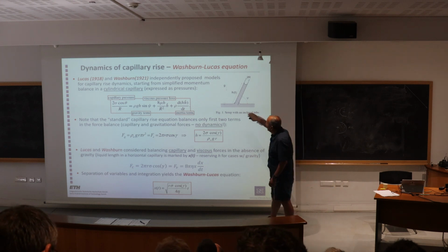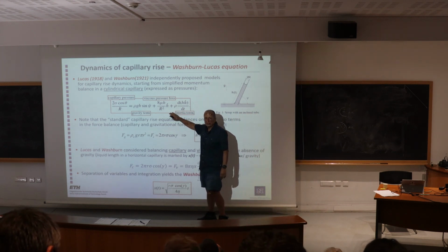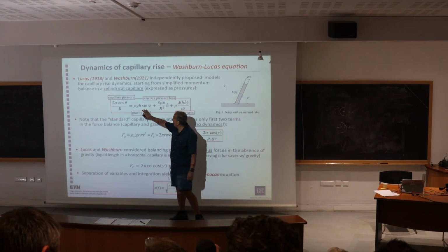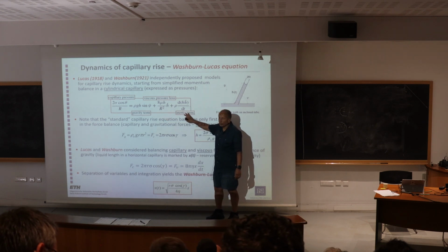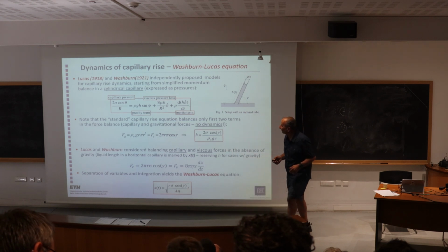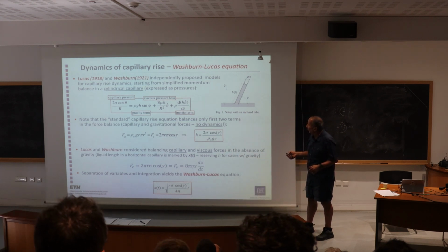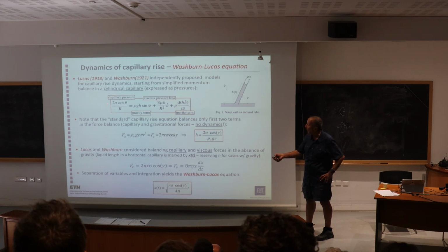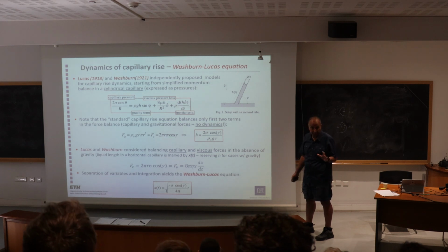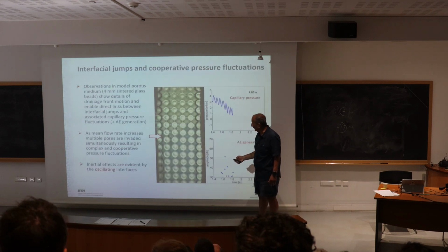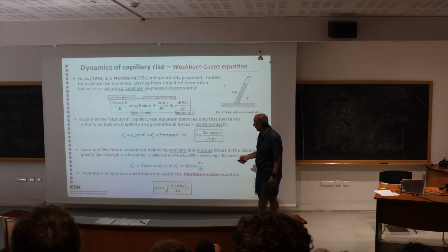And so this is the general force balance equation for capillary rise, and maybe there are some dark forces we're not aware of, but we have gravity, we have viscous, and we have inertial forces balancing the capillary drive, if you wish, or capillary pressure. What we've done so far is we basically just balance these two terms. We balance capillary pressure with a gravity term, and we end up with this capillary rise equation. Okay, so far.